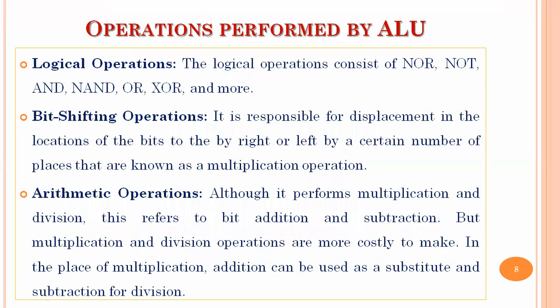So some operations performed by the ALU are, as we discussed, logical operations. As in the name, logical operations could be performed like NOR, NOT, NAND, or XOR, XNOR, and more. Bit shifting operations are also there. Some barrel shifters will use the ALU to shift bits from one point to another, or to shift by a specific number of bits, either left or right. That is also known as the multiplication operation.